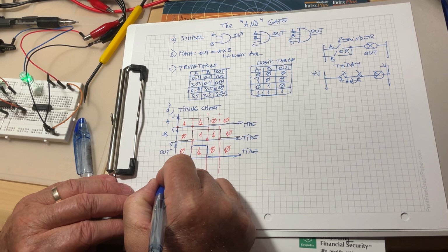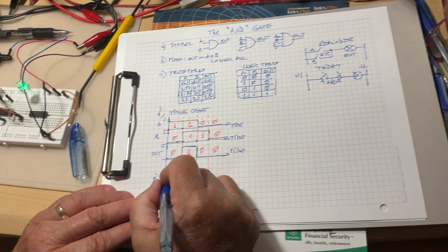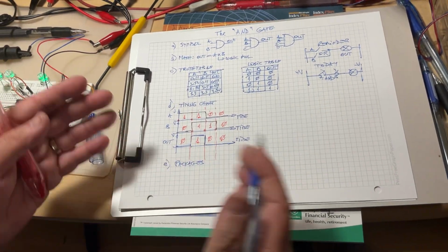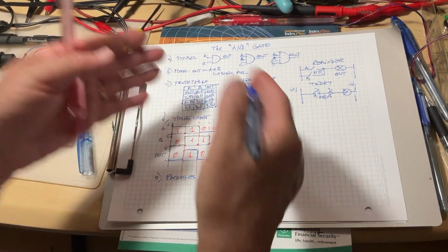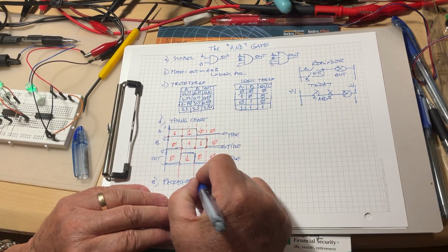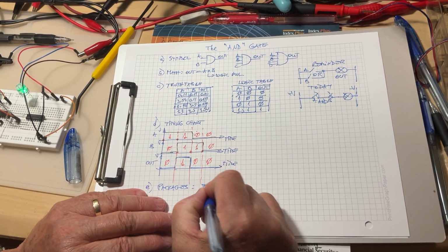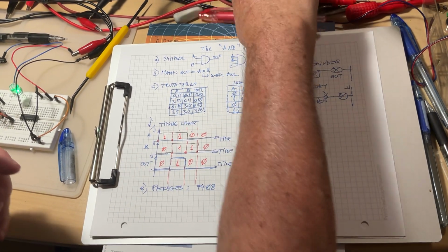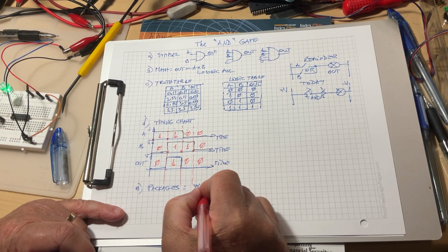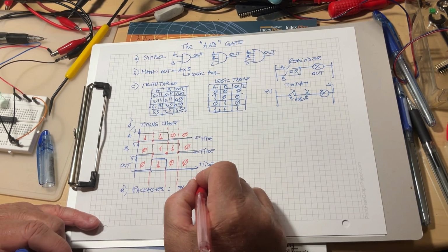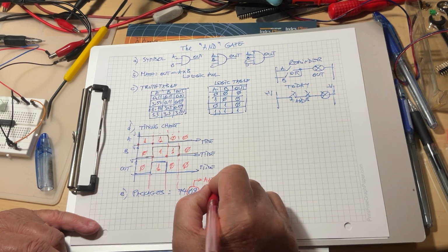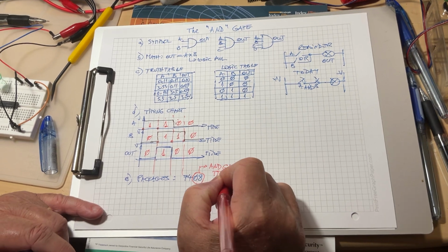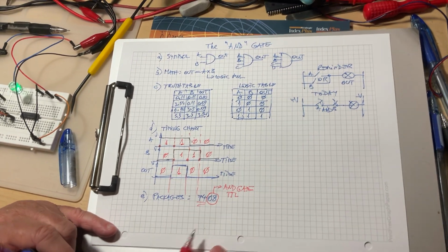At the point E, I'm going to put here packages. Are there any packages containing this gate implemented inside? Of course they are. Example, 7408. So when you see that number here, 08, this is identifying the AND gate in TTL. Why TTL? Because of 74, now you know.